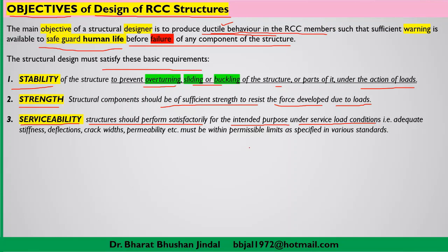That means it should have adequate stiffness. And if there is any deflection, crack width, or permeability, then these must be within permissible limits, and these permissible limits are clearly mentioned in various Indian standard codes, such as IS 456.